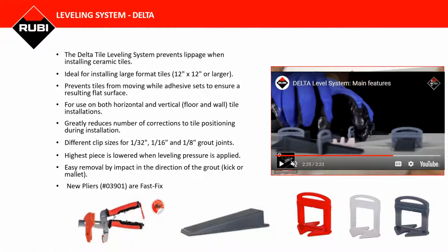So when you're doing your panels, you still need to make sure that you get your substrate nice and flat. I know Jim and the NTCA and other manufacturers have preached that: get your substrate nice and flat. The leveling system is there to help level out the tile. There's bends in tile. It helps bring that down into your mortar and secure it. So it's not a cure for an uneven floor. You still must level out your floor, and then you use the system to get that tile to be even.